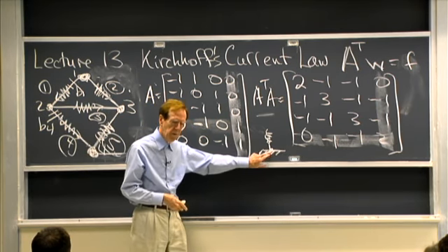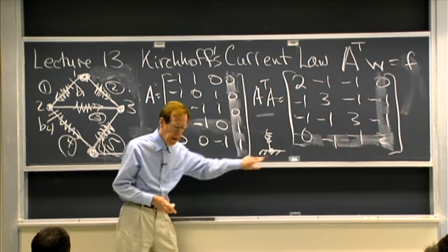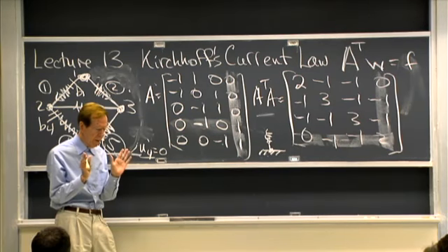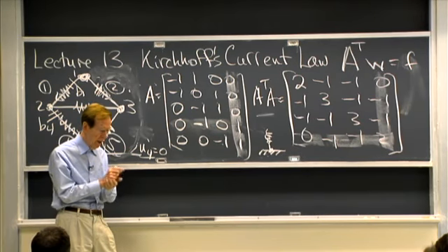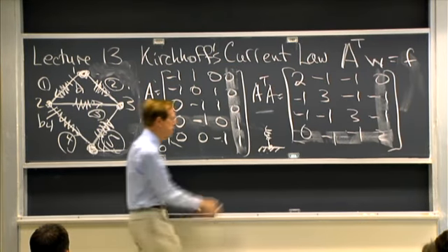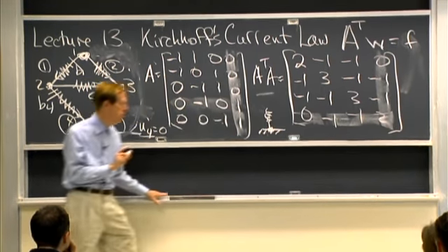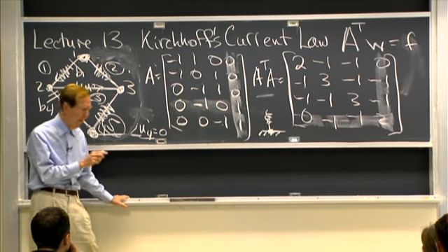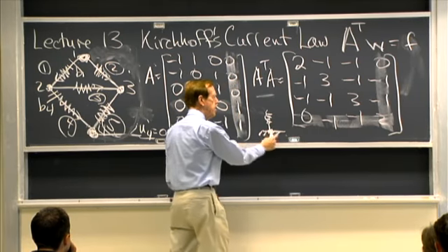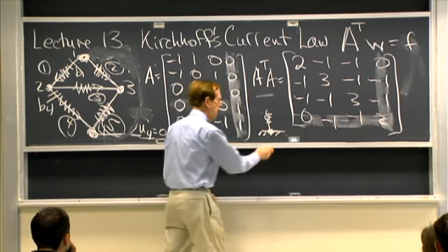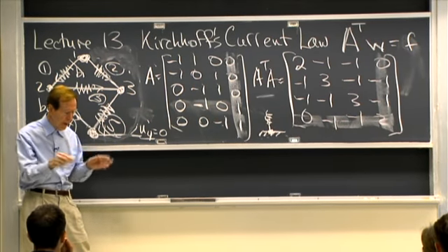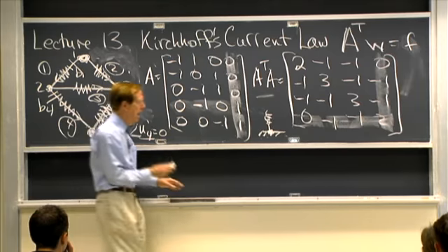A transpose for this, with this fixed end here, what was the thing with A transpose at that fixed end? We did not write the equation A transpose W equal F at this point. We did not write the force balance equation at that point. That when I fixed U4, in this case it was the displacement, so I'm fixing it at 0 displacement, I didn't have a force balance in the A transpose part at this node.